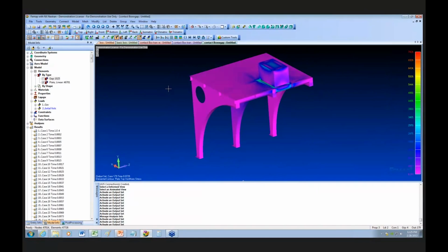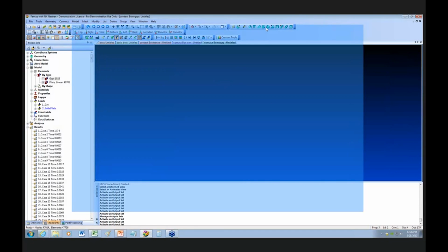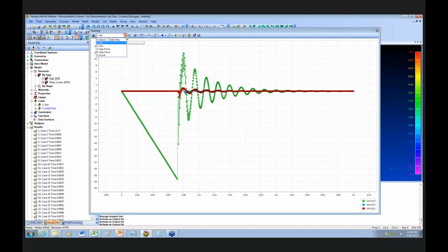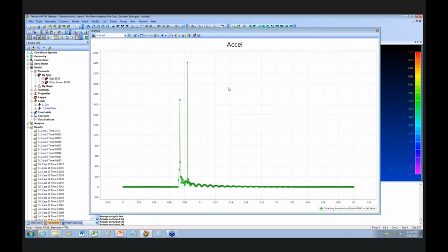And let me see if I can explain that. I'm going to bring back my plot right here. This is the new FEMAP 11 plot. And I'm going to come over here and turn this on. I'm going to point out two things here because I see we're running out of time. I see a couple of spikes here, where this is accelerations in the y direction. We have some spikes here, and I think that's the reason we're seeing this high stress.